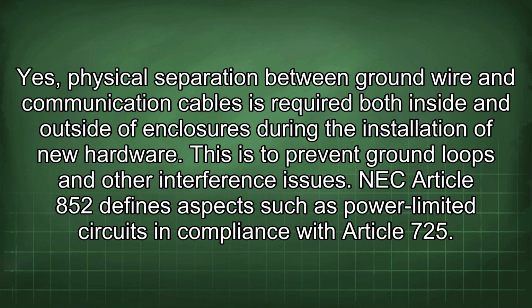Yes, physical separation between ground wire and communication cables is required both inside and outside of enclosures during the installation of new hardware. This is to prevent ground loops and other interference issues.